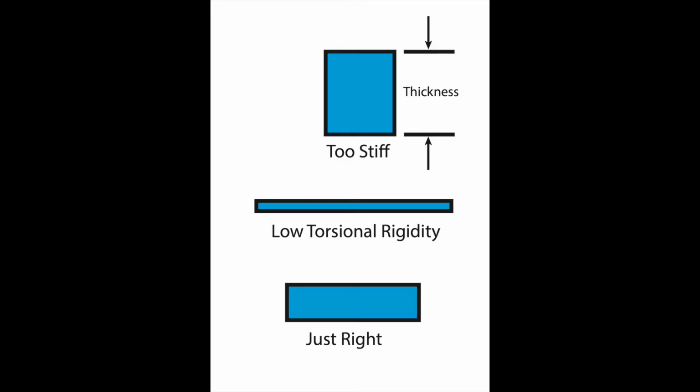What factors produce high torsional rigidity in a ski? Remember that I said torsional rigidity is a combination of a material property and a geometrical term. Let's tackle the geometry first. At any given point along the length of the ski, the cross-section is essentially a rectangle. Rectangles have width and height. The height or thickness of the ski contributes the most to the geometric component of the torsional rigidity. But if the height is too great, it will be too difficult to bend the ski into reverse camber. The proper strategy here is to minimize the width so that the emphasis can be put on the thickness.